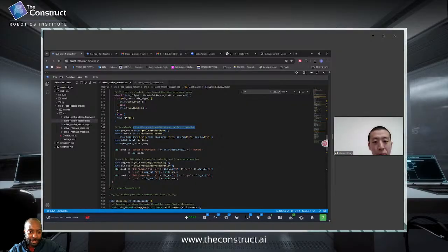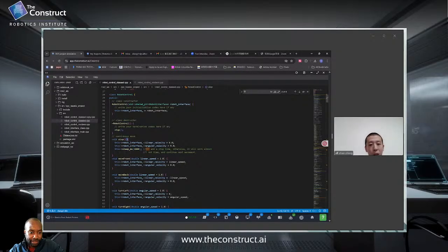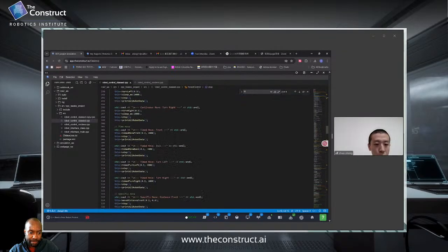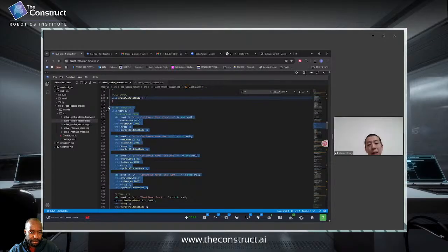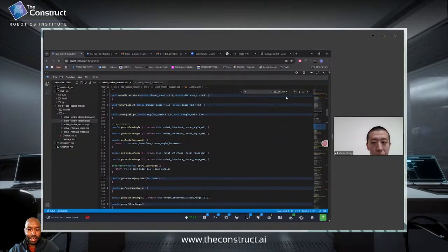Here I add a stop time for the stop, because when I tested in the simulation, if it didn't stop for enough time, it would have momentum. If you are moving forward, you can't stop immediately. So you're trying to bleed out momentum so that it doesn't jerk when it stops. Yes. When I tested whether turn right and turn left could come back, I found there were always some angles that made the robot turn right a little bit, so I added this stop. It's good that you figured that out.